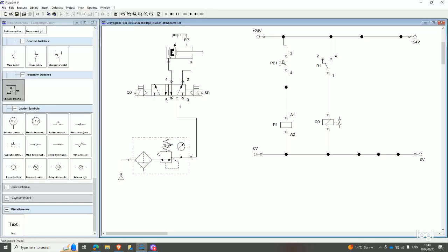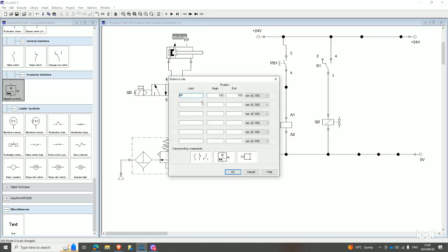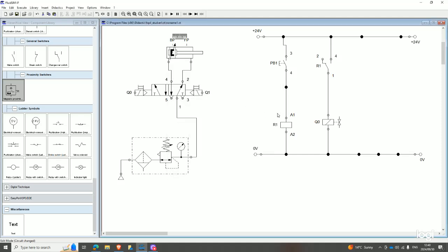So first, when a push button is pressed, right? But we also need to detect when it's at the back end position. So now we'll label a position, we'll call it the back position, which will be 0 and 0 at the rear end. And then to fulfill that second condition, let me just create space here. They are saying we'll use an electromechanical limit switch, so let me just expand this side.